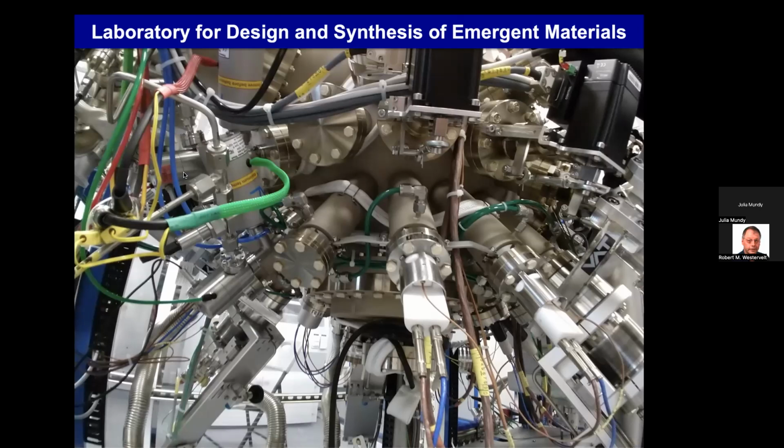And it was recognized in the 70s that there was this so-called contradiction between ferroelectricity and ferromagnetism, which is just a materials limitation. Ferromagnets were materials in the middle of the periodic table with half-filled D shells like iron and cobalt. And ferroelectrics are materials with full D shells or empty D shells like titanium that often gave these displacements in the vacuum. So we discovered the first material where these two properties can coexist at room temperature. There have been a few materials where they can coexist, but at 10 Kelvin or something like that.